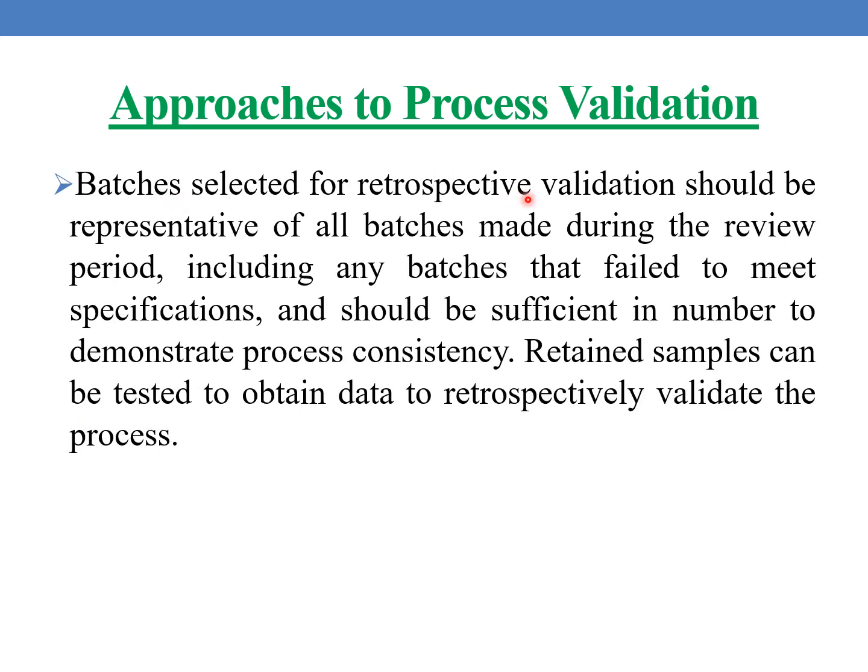Batches selected for retrospective validation should be representative of all batches made during the review period, including any batches that failed to meet the specification, and should be sufficient in number to demonstrate process consistency. Retained samples can be tested to obtain data to retrospectively validate the process.